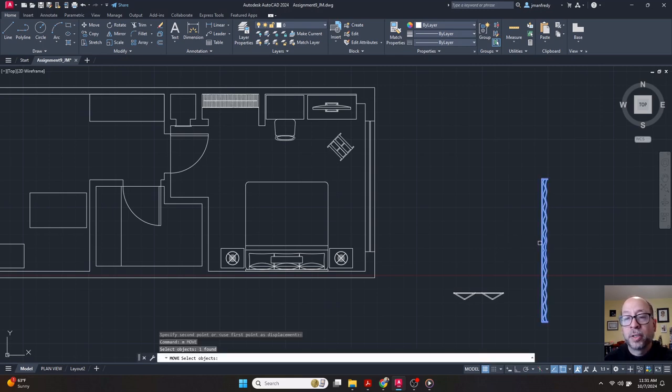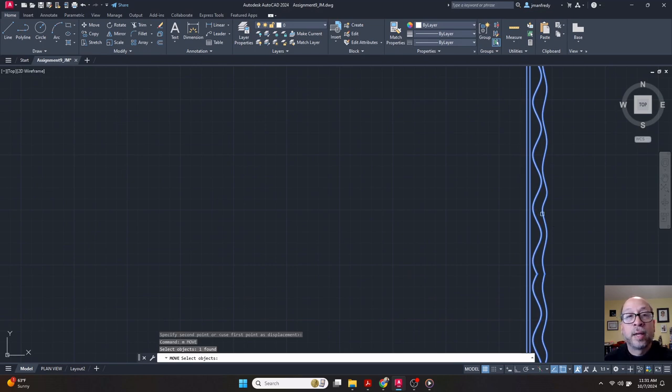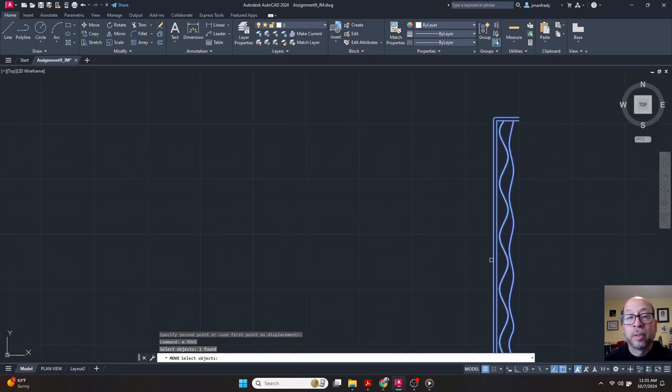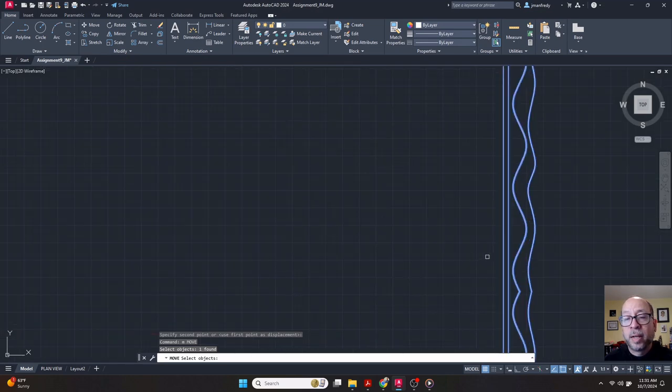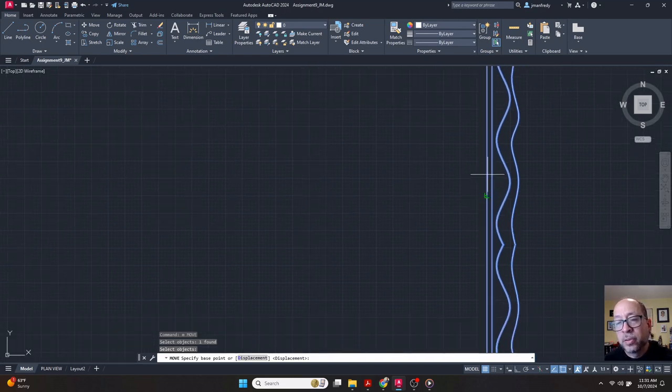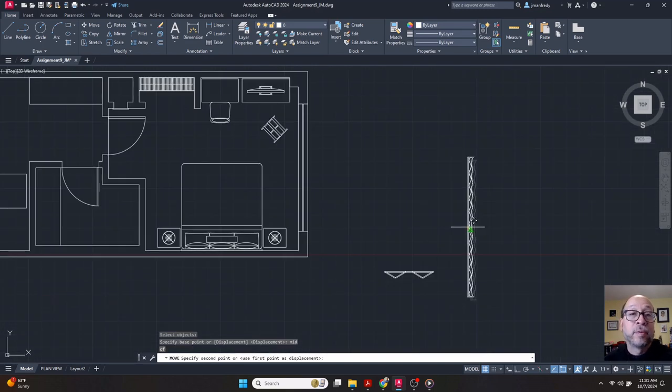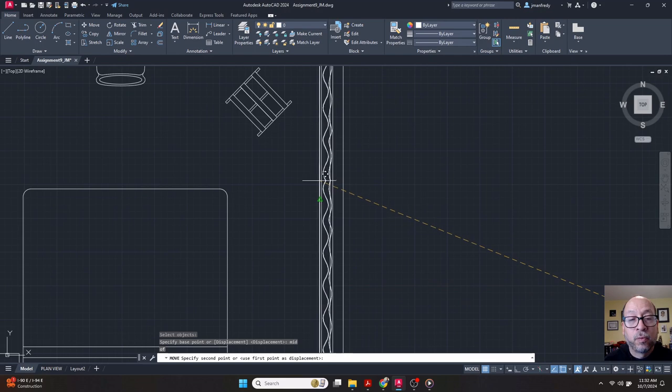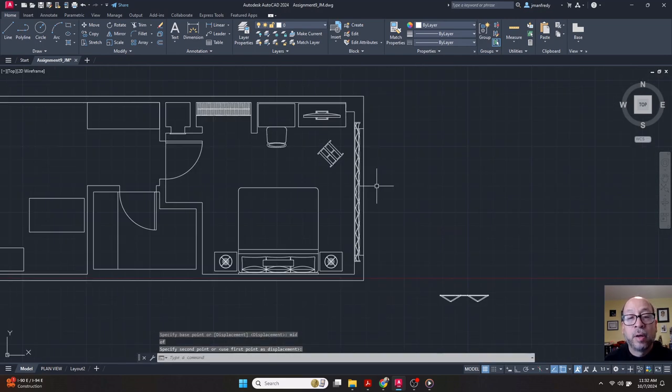I'm going to move this object here. There's a curtain here with wavy lines, and then here we've got a valance at the top of the curtains. I'm going to find the center line of that curtain here. And if it can't find it, because right now it's looking for a perpendicular snap, I can type MID, enter, and it's looking now for the midpoint, which is actually down there. Click. So that's a good thing to have. I overwrote the options, and I only chose midpoint to search for. And that's what happened. Here, I will look for the midpoint there. It's green. Click.